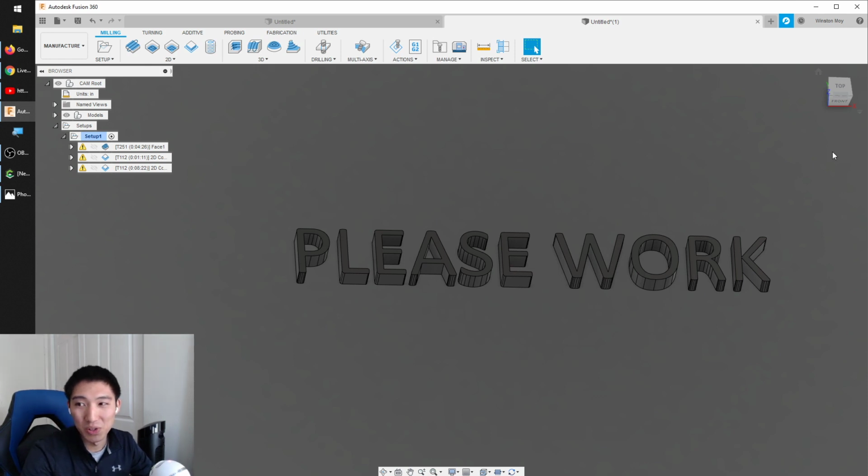Best way to start learning Fusion 360 for woodworking and CNC: find a simple project where you can focus on just using some basic toolpaths like 2D contours and 2D pockets. Lars Christensen, he works for Autodesk. He has a great set of videos that basically hold your hand through the learning process. Autodesk's own resources are pretty good. Their tutorials are very solid. For more advanced toolpaths, you can check out NYC CNC.